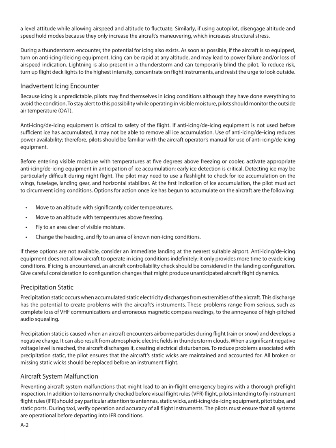Anti-icing/de-icing equipment is critical to safety of the flight. If anti-icing/de-icing equipment is not used before sufficient ice has accumulated, it may not be able to remove all ice accumulation. Use of anti-icing/de-icing reduces power availability, therefore, pilots should be familiar with the aircraft operator's manual for use of anti-icing/de-icing equipment. Before entering visible moisture with temperatures at 5 degrees above freezing or cooler, activate appropriate anti-icing/de-icing equipment in anticipation of ice accumulation. Early ice detection is critical.